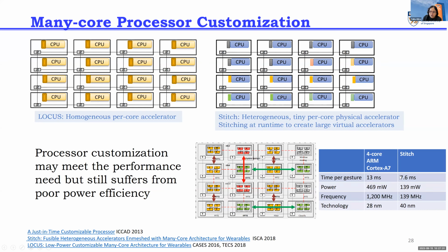Now, if you look at this particular architecture, it actually satisfies the three things that I was talking about. First, it satisfies parallelism. It is an array of simple processing elements. It has very simple hardware, so you can see these are not cores. These are just simple arithmetic logical units. So it's very, very low power, and it's exposed to software, so everything can be done by the compiler. The compiler does the heavy lifting of mapping things onto this particular architecture.